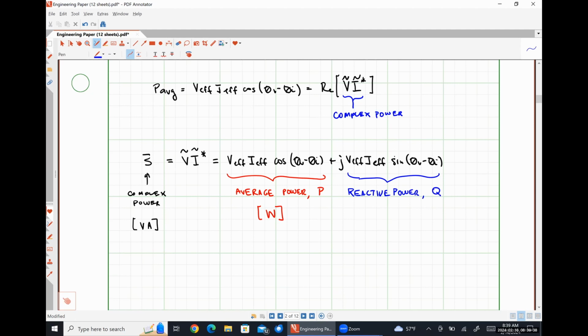Commonly given the symbol Q. So this is the imaginary part of our complex power, but it has a very non-imaginary purpose. I'm asking because you work in this industry, if I say anything out of turn, please correct me. What the reactive power represents is temporary energy storage in our system. So we only have reactive power whenever there are capacitors and inductors in our system.